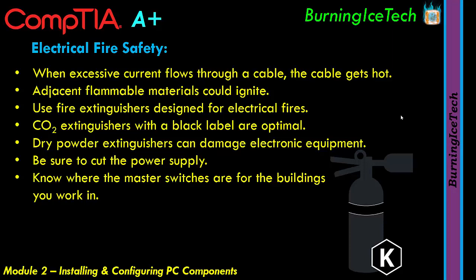Yeah, I mean, if you've got a hot cable and you've got something near it that's very flammable, liquid perhaps, that speaks for itself. Use fire extinguishers designed for electrical fires. Now, depending on which country you're in, you'll find that most common fire extinguishers have some categories written on them. You'll generally find category A, B, C, and D. So make sure you use the right fire extinguisher for the right fire.